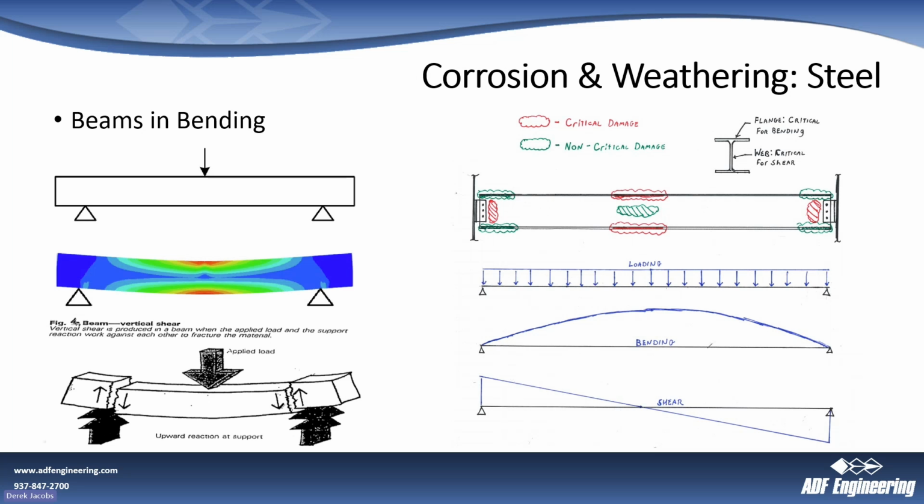If you have a beam with loading in the middle, even if it's a point load, or a distributed load, generally you can assume that the amount of bending is the highest in the middle, right? When you do that, you'll have compression stresses that build up at the top, and then tension forces that build up at the bottom. And all of these are at the far extreme tops and bottoms of the beam. So that's where those stresses are.